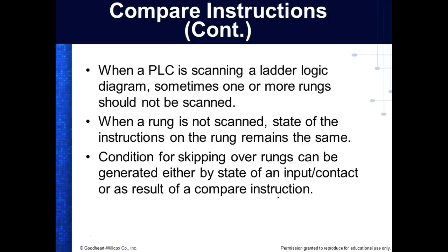When the PLC is scanned in a ladder logic diagram, sometimes a rung should not be scanned. When a rung is not scanned, the state of the instructions on the rung remains the same. Conditions for skipping over rungs can be generated either by the state of an input contact as well as the result of a compare.